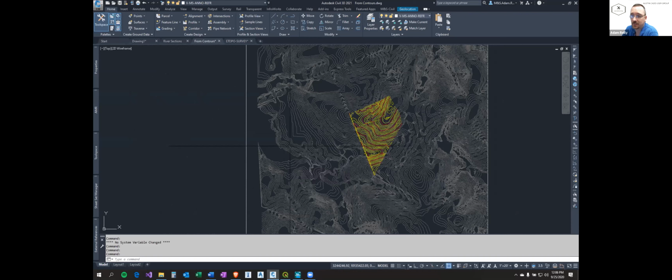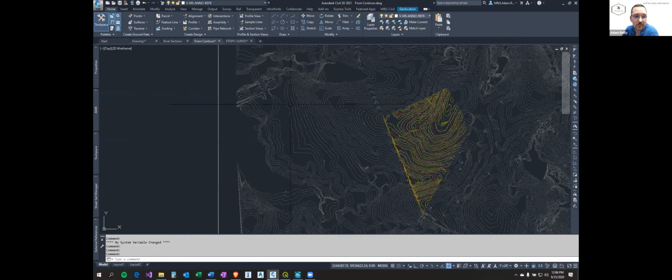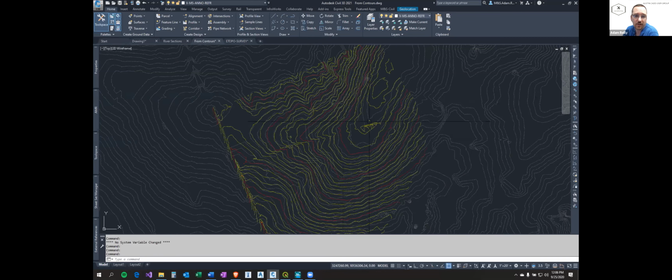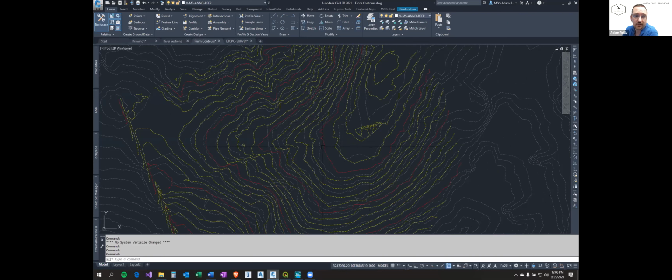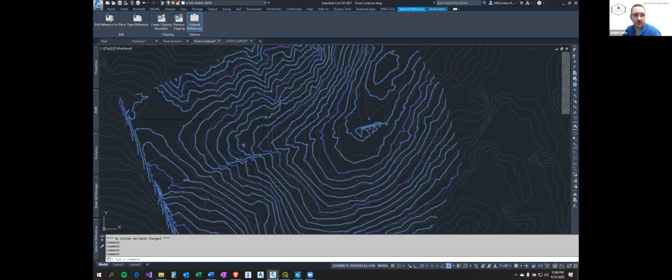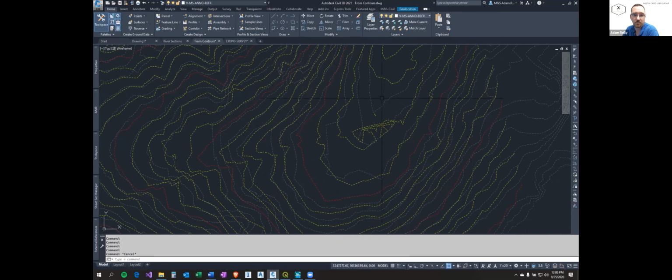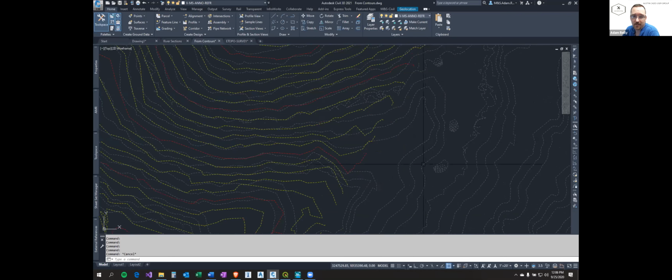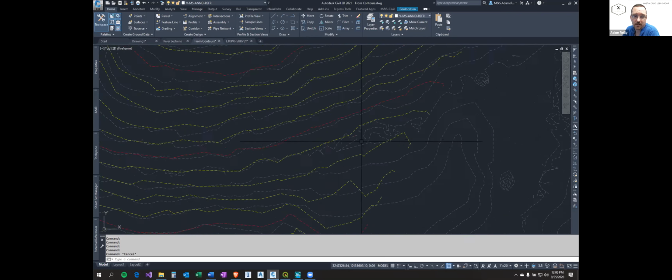But because they're contour lines, you're going to see a lot of issues. Because they're 2 foot, you're missing stuff. It's going to interpolate between, and you're going to see junk like that, or you're going to see missing stuff. Over here, these lines, the surface is the actual survey. So you can see that it's missing some information just because it's 2 foot. It shows all kinds of stuff like this.